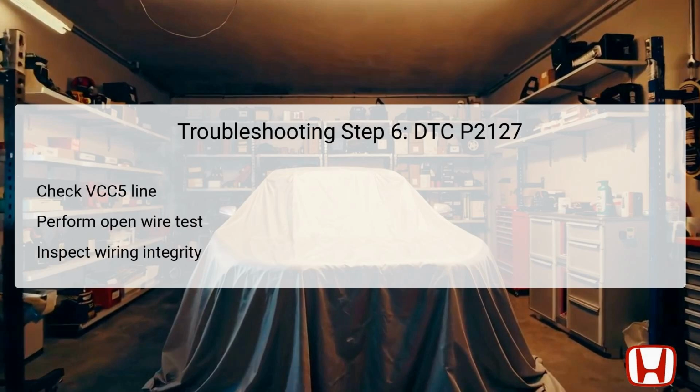The final troubleshooting step necessitates turning the vehicle to the off position once more. We start by jumping the SCS line with the HDS and allow it to reset for over a minute. The next requirement is disconnecting the PCM connector A, 50P. Then by connecting terminals A and B, pin number 1 of the APP sensor connector and body ground, you can test for continuity again between the test points.